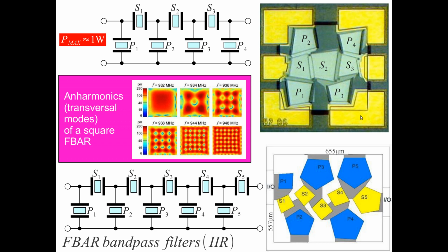This kind of filters are nowadays typically installed inside mobile phones on those frequencies where my mobile phones operate in duplex. When they are transmitting and receiving at the same time, the only solution are these film bulk acoustic wave filters. They can even be integrated in the same package as the transmitter output stage. On many occasions, these filters here have coaxial connections with one electrode grounded, but they can also be built as differential circuits. And this is also typical of today filters installed in mobile phones.